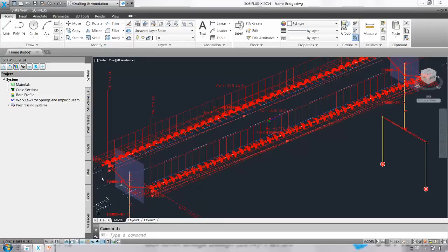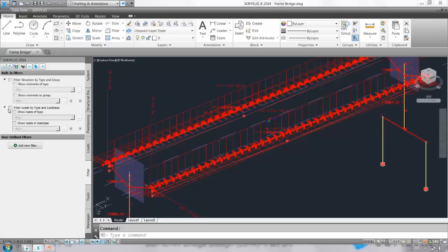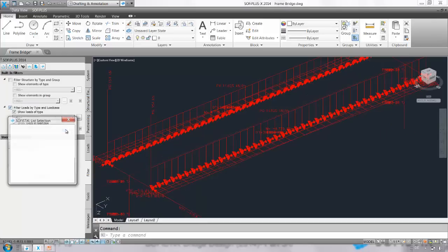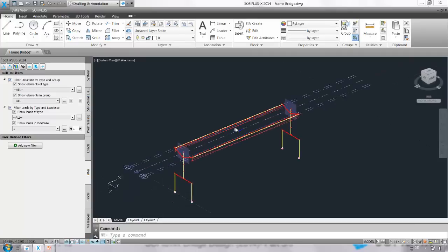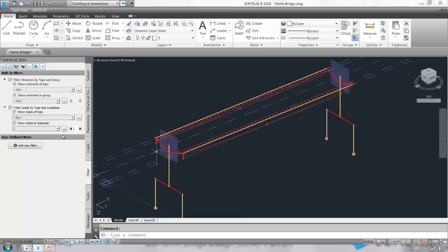And now I would like to show you the additional loads which I have prepared for the superposition. So we're starting with load case number 1. Load case number 1 will be needed for the self weight. Then we have load case number 2, that's for the cantilevered parapets.